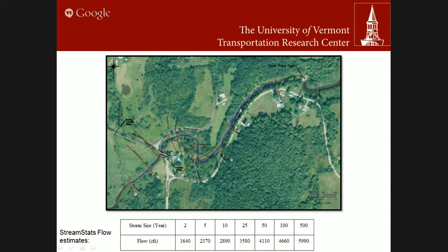And so we came up with a bunch of different designs, but the one I'm going to focus on is the fuse design itself. We first had to come up with a hydraulic analysis to get existing conditions of the site. So we created a HEC-RAS model using cross-sectional data from South Mountain Research and Consulting Group.